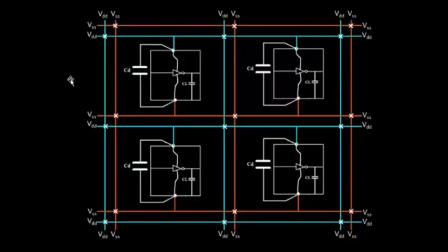So this is the reason that in recent chips, there are multiple power supplies, multiple VDD and VSS ports. There are multiple pins for VDD and VSS. This is exactly the reason for that. And similarly, let's say there was a line which was going from this point to this point.